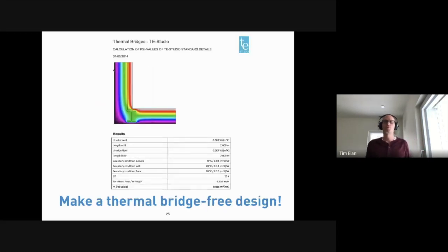Thermal bridge free is super important. Again, I know some of you are into the building sciences. There are standard metrics around this. I won't go deep there, but it is imperative, especially in a cold climate like ours, to keep thermal bridges at bay, just because they also provide a risk on a building science level for early building degradation that we don't want to take. So it's not just an energy penalty, but those are areas where buildings can and will fail. So they need to be dialed out, and that's a design exercise.